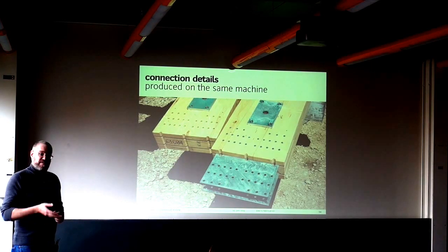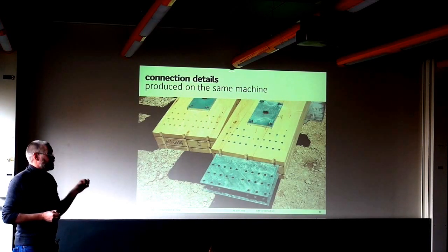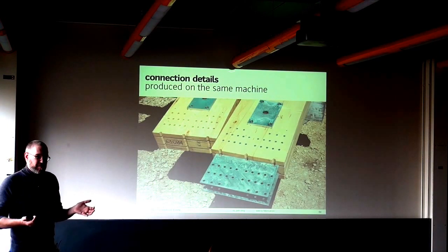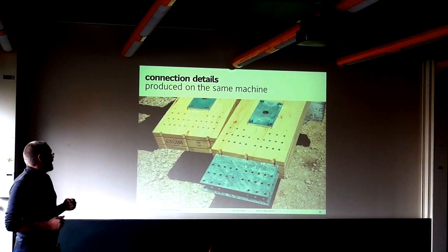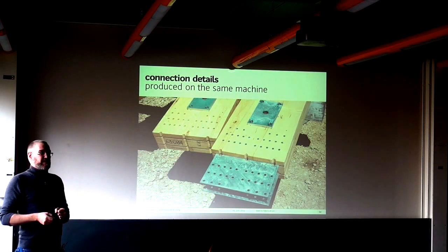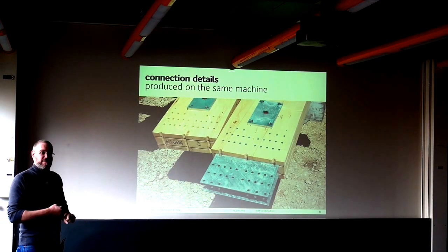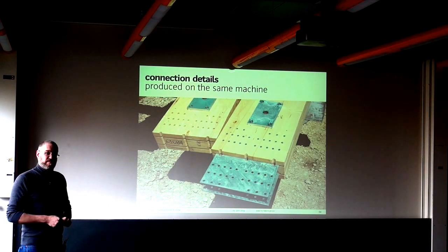It's actually pretty precise. This is one of the precision things that I was talking about. The hole has to have the precise diameter, which is not a problem because you have a drill that usually has a certain diameter, but it has to be positioned within a few tenths of a millimeter to meet the holes in the steel plate and to be able to transfer the loads. For the hexagonal thing, you also had literally no tolerances.